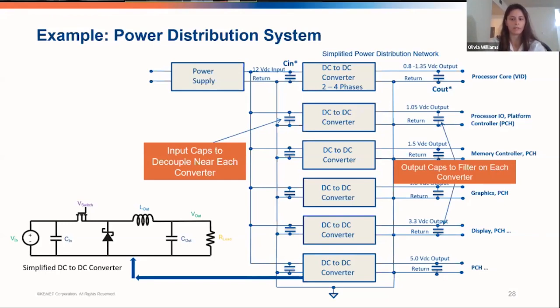So I guess when you consider that, we assume a matched transmission line with suitable characteristic impedance feeding that active device. And what really matters there is that the impedance that feeds it, that low one that we calculated, reaches the end device or the IC. So as long as you can do that, precise location might not be too important, but when in doubt, just place them on the input and the output.